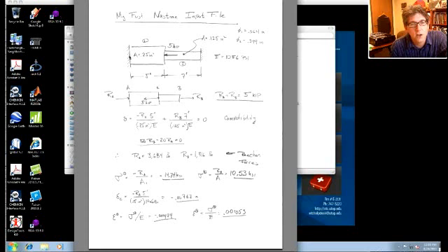So here's this compressional 15 ksi stress in this one, and an extensional 10 ksi stress in this element. Then we can get the displacements of the nodes. Obviously, these nodes displace 0, but this node displaces 7/1000ths of an inch to the left. And then we can get the strains, and here are the strains in the elements.